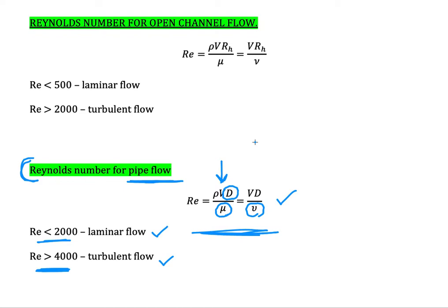If our conduit is rectangular or triangular, we don't have a diameter for that shape. So we change the equation by the idea of similarity or dimensional analysis. I'm not going to explain that. To simplify, we replace the value of D with the hydraulic radius.